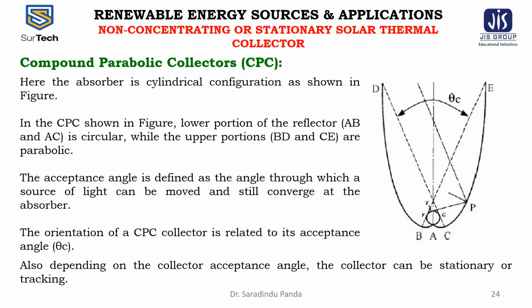In practice, bigger angles are used to enable the collector to collect the diffuse radiation at the expense of the solar concentration ratio. Smaller concentration ratio CPCs are of the greatest practical interest.